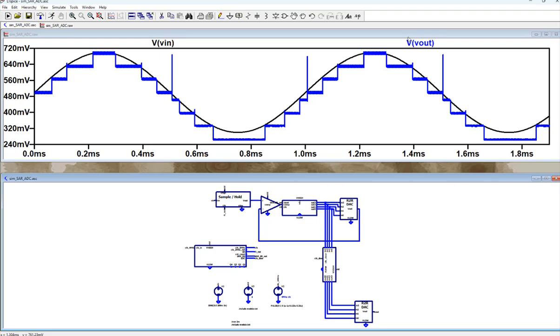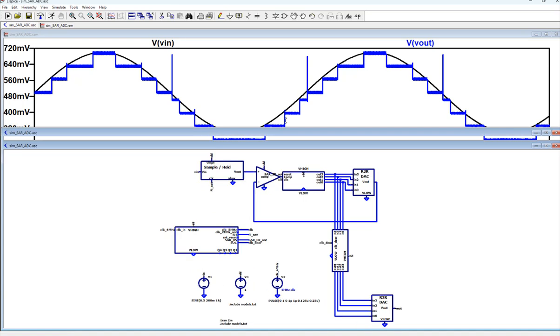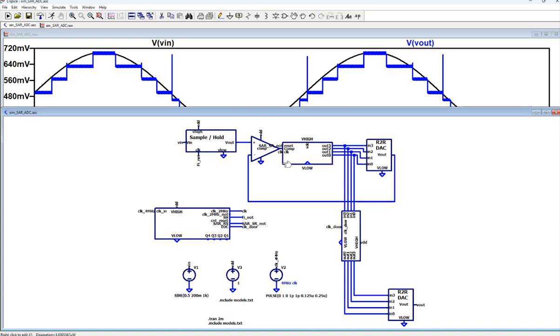16 stages. And this is the technology file I'm using for LTSpice right here. The VDD is 1 volt because it's a fake model. It's not really a fabricatable model. It's a 50 nanometer technology, but it's fake from the textbook. So that is a small channel technology and can handle 1 volt VDD. I think the threshold voltage is probably like 0.3, 0.4 volts. It's pretty low.